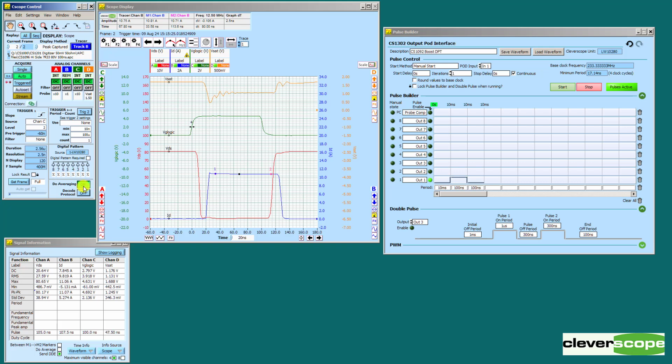The next channel is the logic drive, and here we can measure the delay between the logic drive. Let's go from middle to middle. So there, I'll click 1. I can choose where to measure to by using the controls above the graph. Say I want to measure V to ID, I click on the ID and then go down here, and now the markers and tracer will be on ID. So I'll go 2.